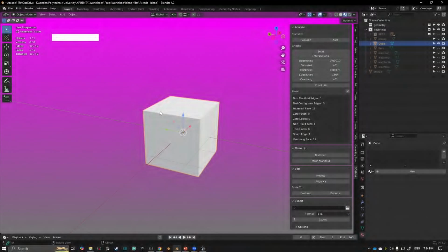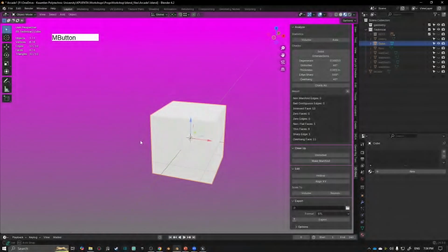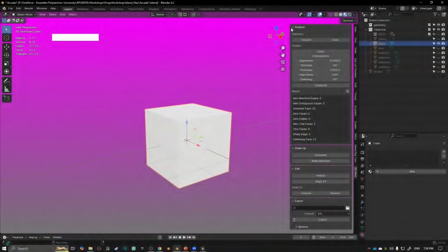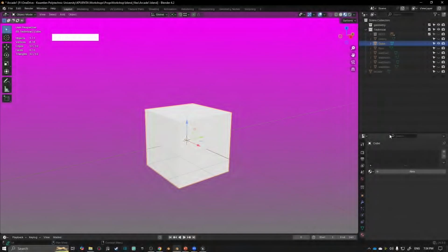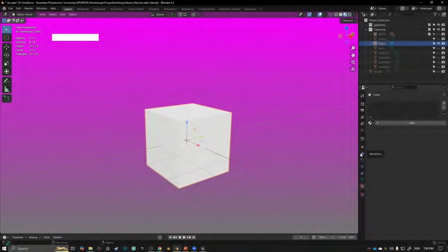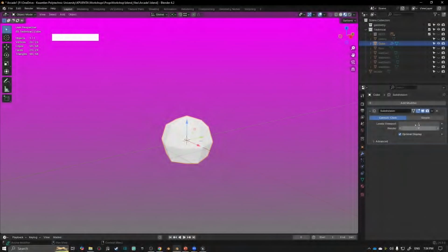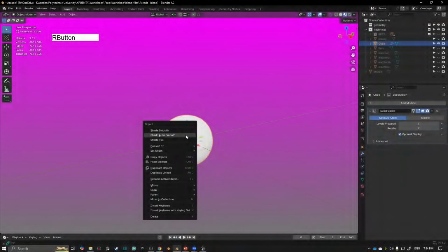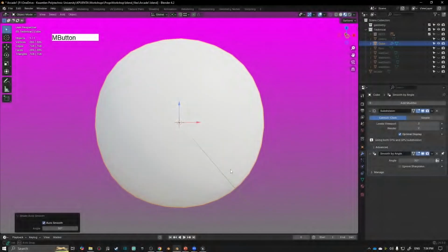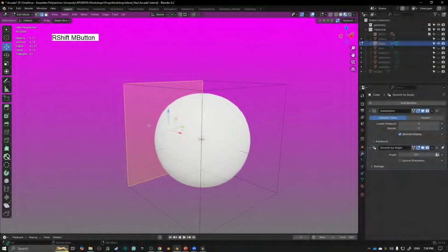Okay, so using supporting edge loops or the bevel modifier, is one better than the other? So that depends. Let's say I have this object here, and I want to subdivide it. So I want to have more geometry. I can click here on the modifiers, and I can go generate subdivision surface. Let's crank up the number. So it turns my cube into a sphere. I don't want a sphere. So I'm going to go back into edit mode. I'll hit tab so I can see my cube.